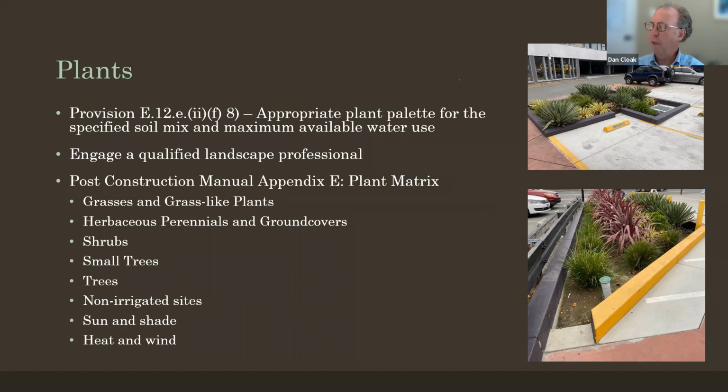Or they did the opposite mistake, which was to choose plants that were aesthetic or wanted, but without considering the particular characteristics of the fast-draining bioretention soil. When both go together and the process is understood, I think there are a very broad variety of plant palettes that can be used for different effect.